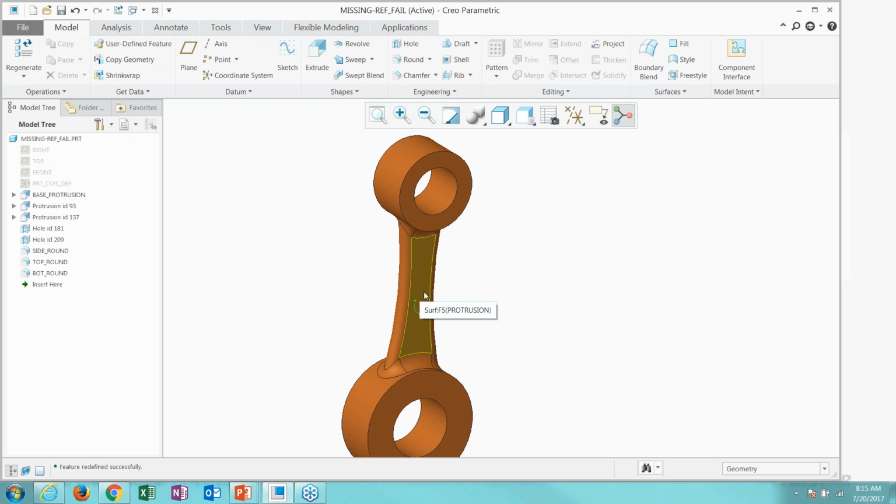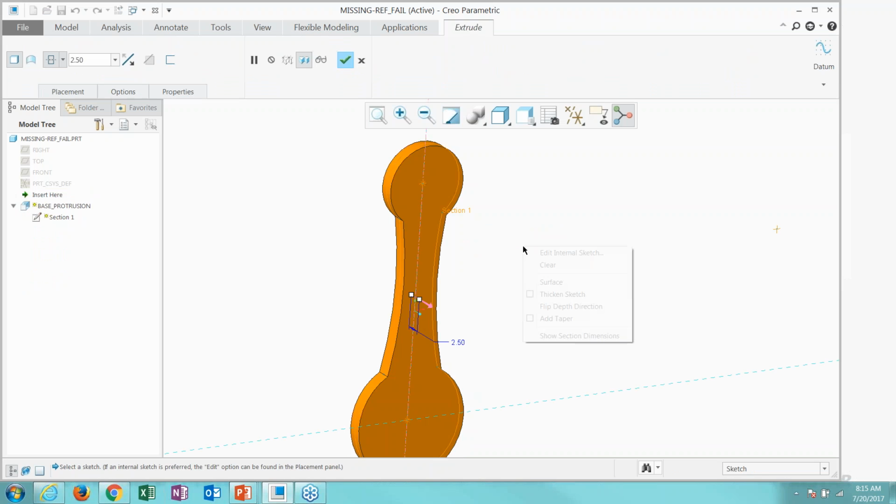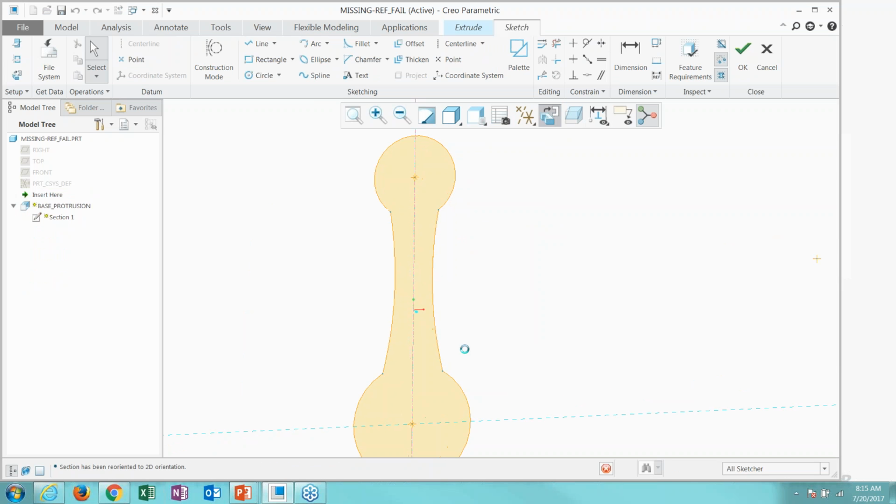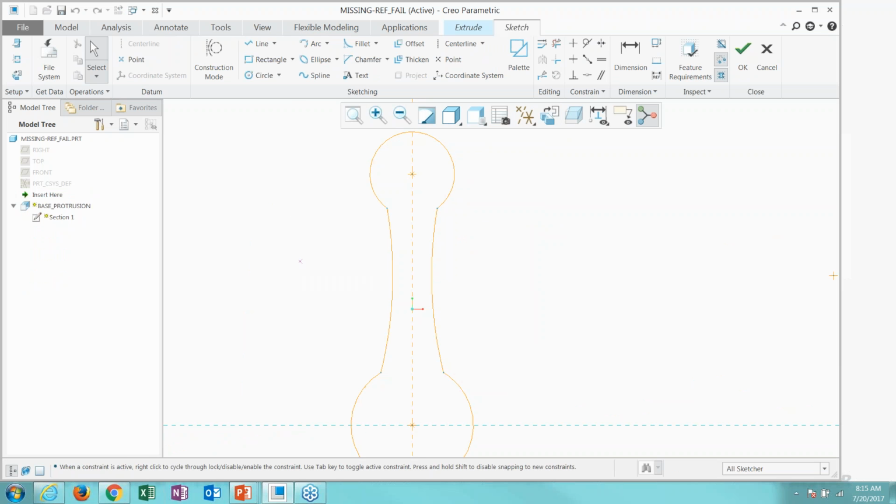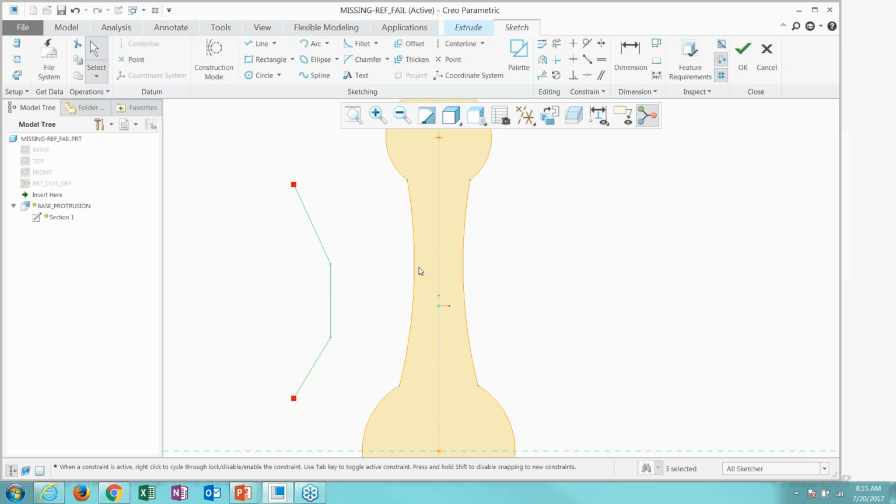And sometimes, when you get a chance, try doing that. You could even replace this with, let's say you had a situation where you had multiple geometries like this. Line to an arc was simple. It was able to replace the ID. How's it going to behave when I have an arc to be replaced with these multiple geometry shapes? Guess what? You could divide. There's a divide tool, as you know, in Creo, which allows you to divide this entity into three, regenerate the section first, and then replace this guy with this, replace this guy with this, and this with this.